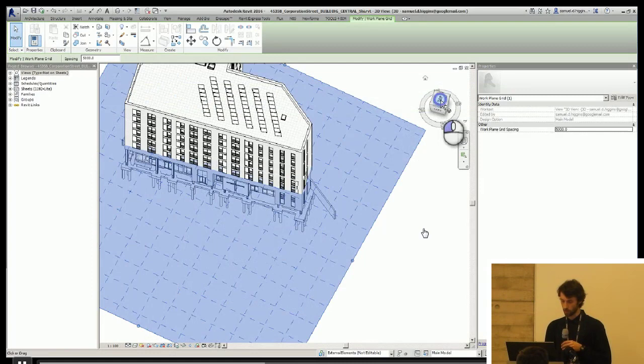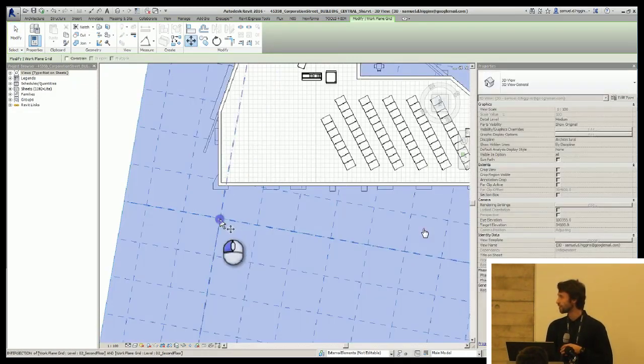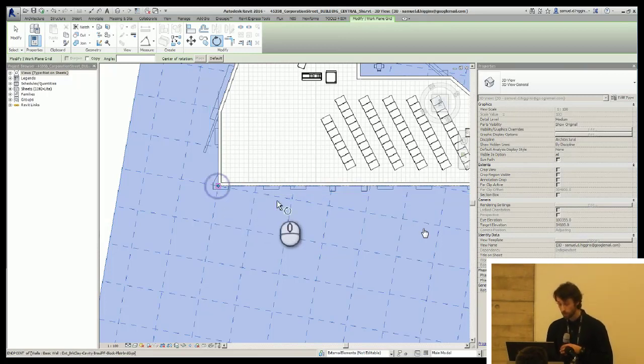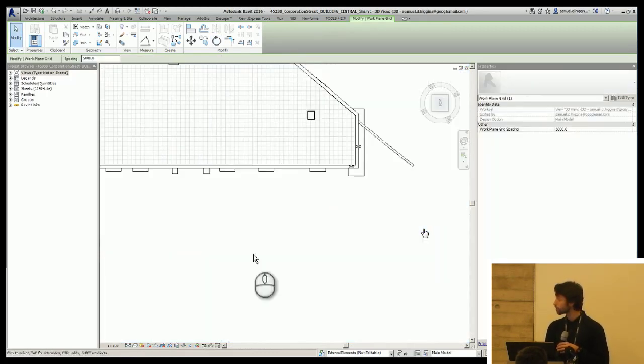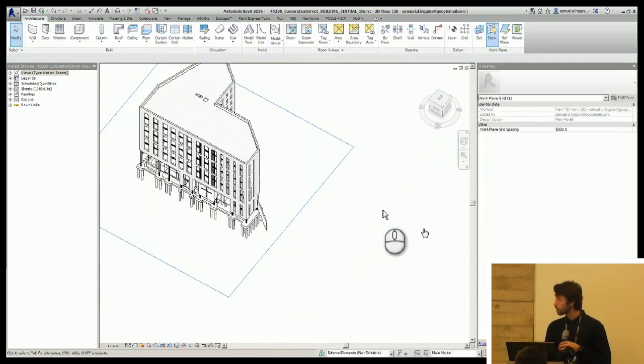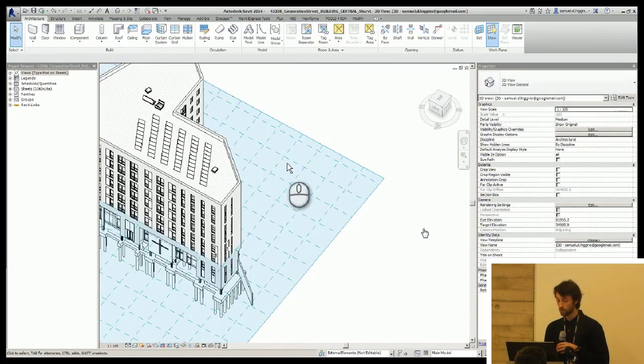So yeah, once we've specified and messed around with the work plane, we can move and align this work plane grid. You can rotate it relative to building elements that you've already done and make it specific to the thing that you are modelling. And the reason this is important is because then when you begin to sketch in 3 dimensions, you will automatically snap to the orientation orthogonal to that of your work plane, which, if this sped up, I would be able to show you.